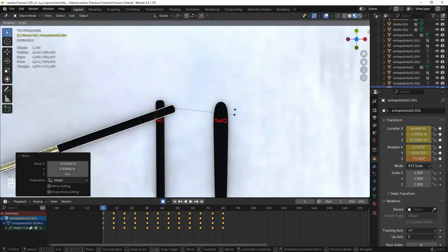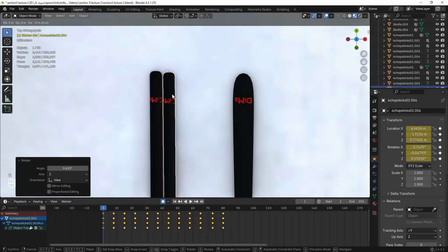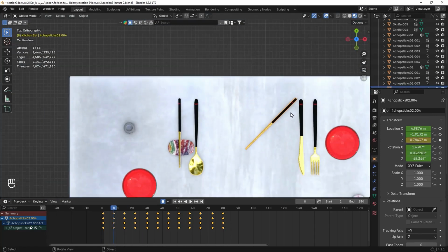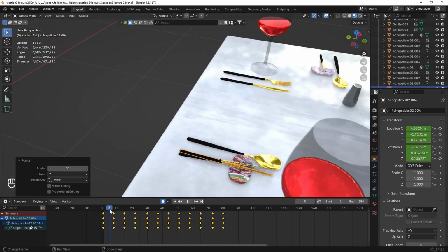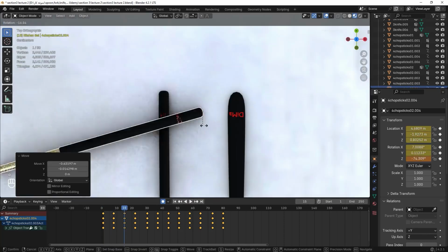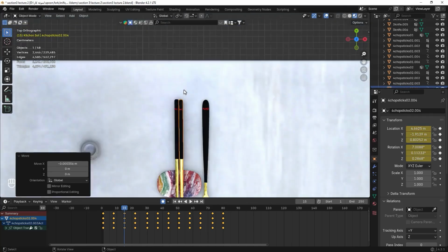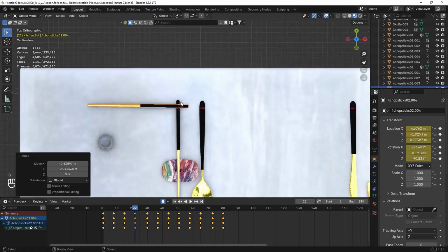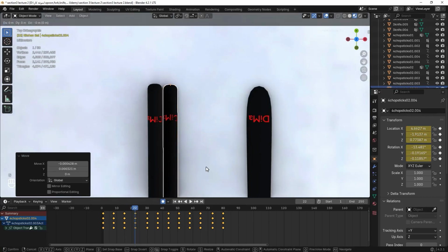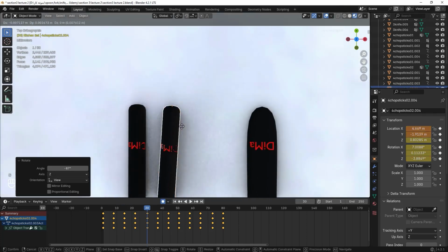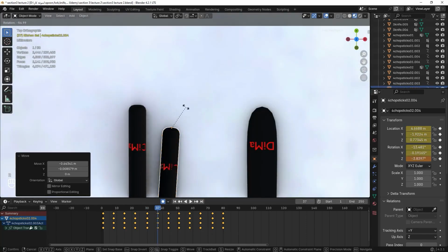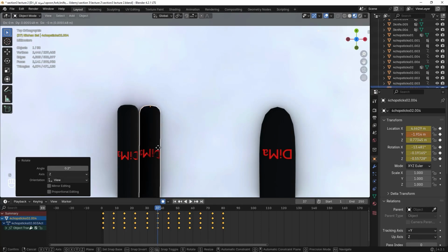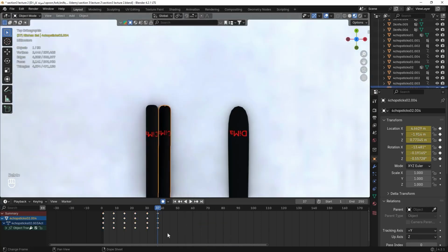So we duplicate the last 2 keyframes and move 6 frames forward and place them on frame 50, and then duplicate the last 4 keyframes this time, and we move it forward 6 frames again and place it on frame 77, and then we set the keyframes by moving and pressing S to scale until we get to frame 80.